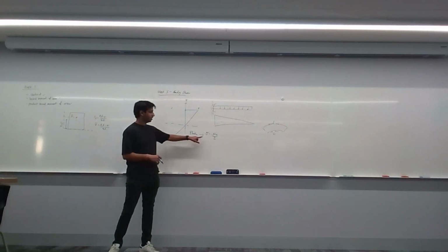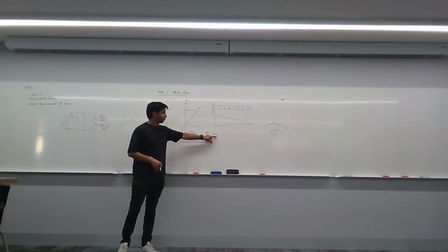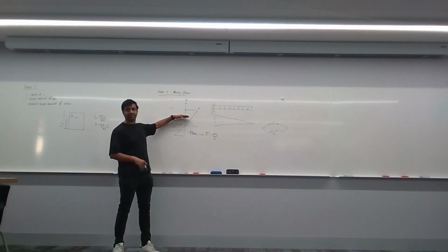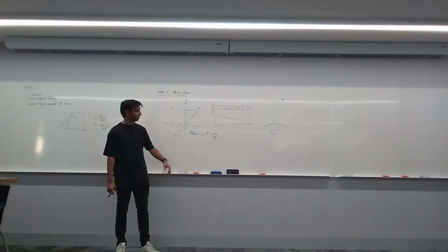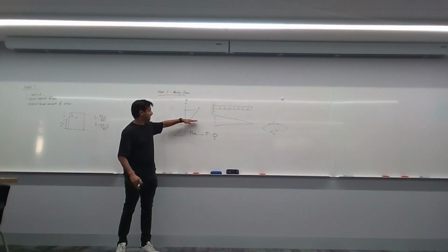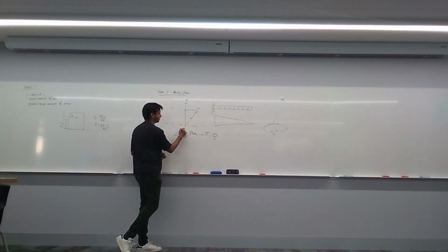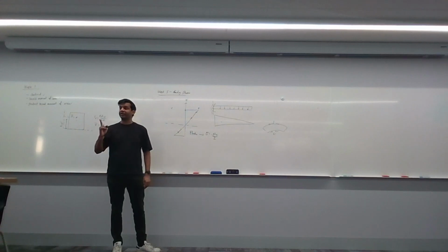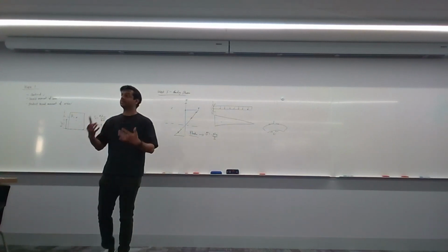So for example, for a given bending moment across an entire cross section and a given y distance away from the neutral axis and a given I value for your entire cross section, you can use this formula to calculate what your stresses will be at any point along the element. So you can calculate that stress, that stress, etc. But the rule is it has to be completely elastic, meaning nothing should have yielded.